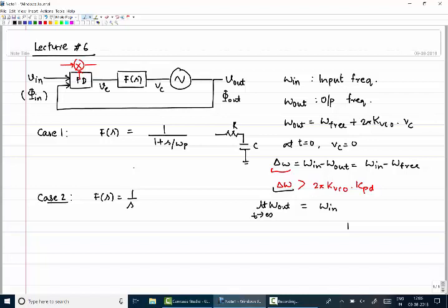Because we found that with the mixer based phase error detector, the voltage error which we are getting, that V error, has an asymmetric waveform. This is what it was having for a mixer based phase error detector. So we thought it has some particular DC voltage which is representative of the frequency error, and if we can amplify this DC voltage by a large amount, actually by an infinite amount, then we can recover the frequency error.